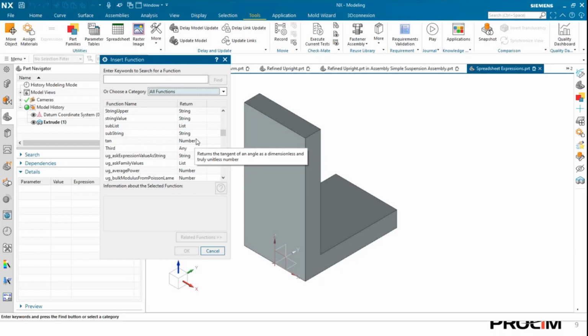Let's say you like to play around with your extrusions and your 3D printing part, and you have your company logo that you want to either extrude outwards or subtract inwards. And oftentimes you do that just whenever you want, or depending on what you're doing. Or let's say you're still in the prototype phase, but every time you use your details tab and hit -10, it says, hey, I was an extrusion and a unite before. There's nothing to unite to anymore if I'm going negative, or at least I'm still in the body. So what's going on here?